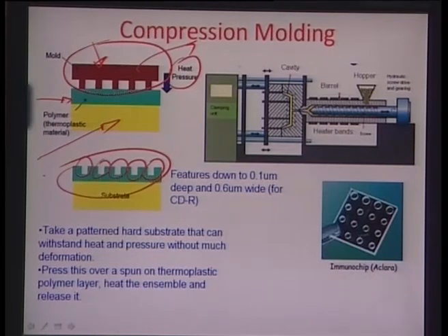This is how you write micro features or structures onto a surface. So, the very common compact disc that we use regularly in our computers or audio equipment is essentially realized using the compression molding process. And another very important technique which is often used is injection molding, which is illustrated here in this particular figure.